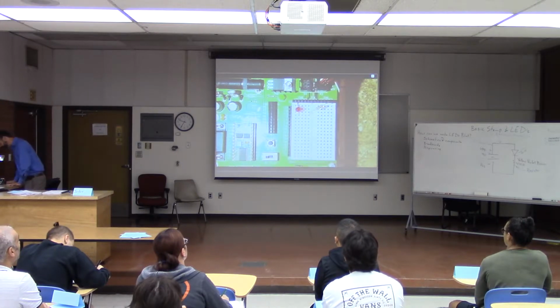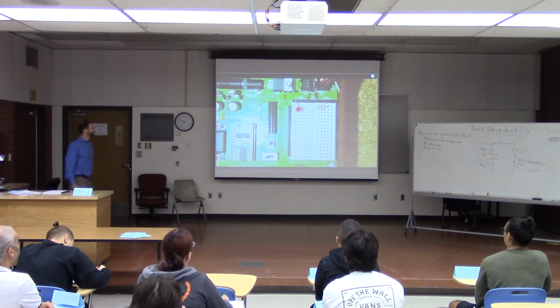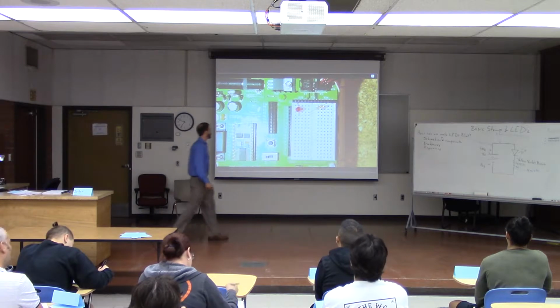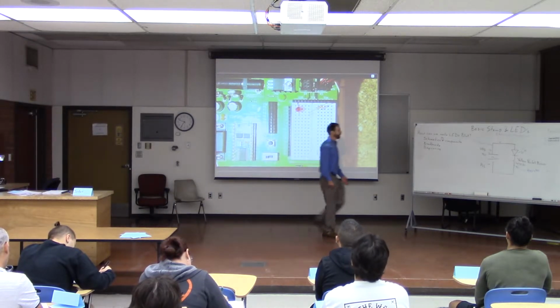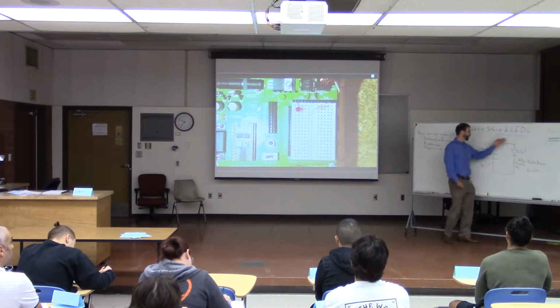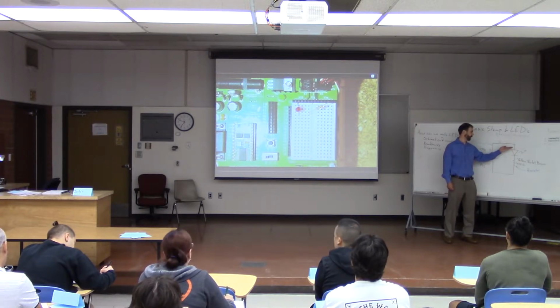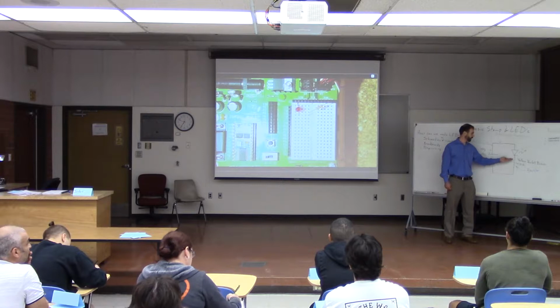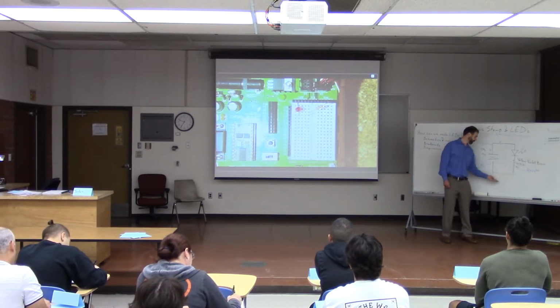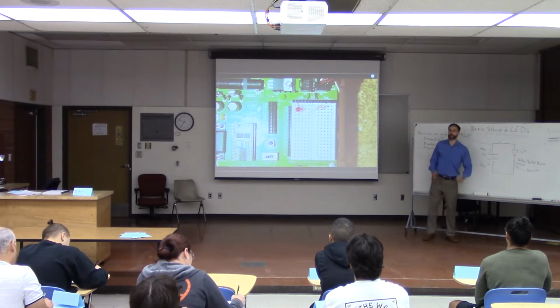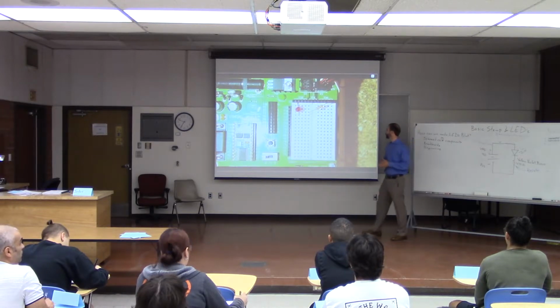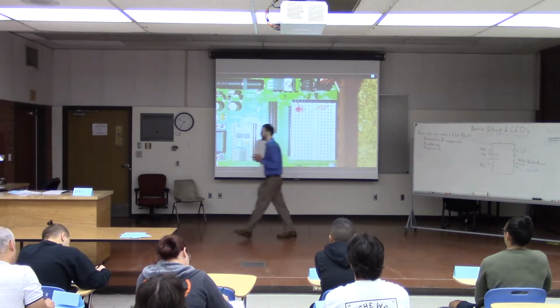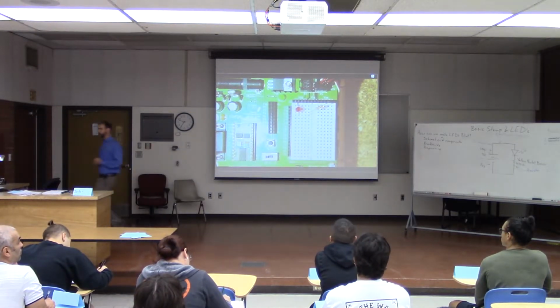Okay. So now we've made all of the connections that we need. We connected the power supply to the anode of the LED. We connected the cathode of the LED to one side of the resistor, and then the other side of the resistor over here to VSS. So now our circuit should be ready to go.